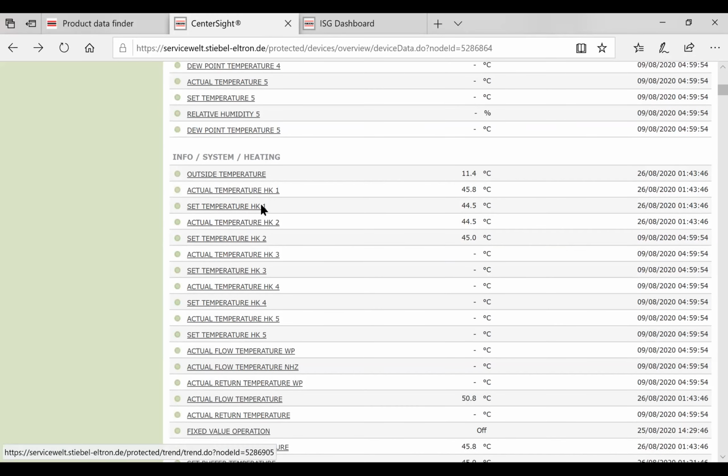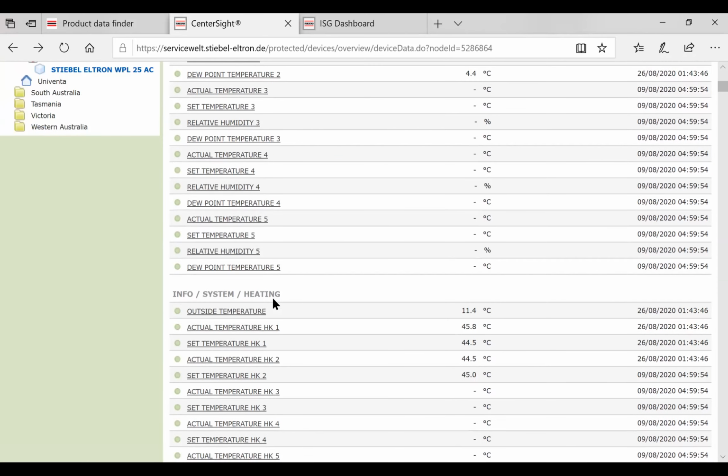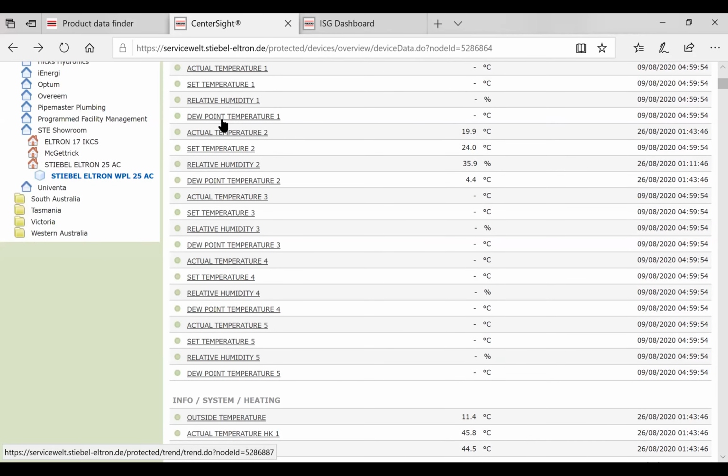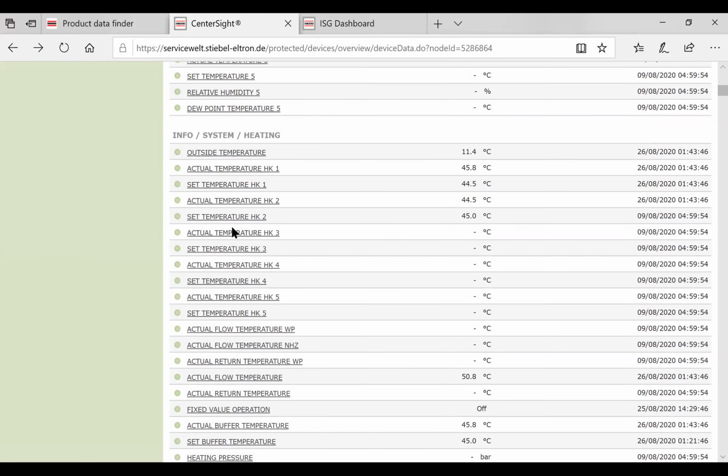We can look at every single heating circuit and see what the temperature set in that circuit is versus what the heat going to that circuit is. Think of a recent job, heating circuits. What I did was I looked at what the set point for a particular heating circuit was, and I looked at what the actual water flow temperature was, as measured on the sensor going to that section. And I could see it was all over the place. I'm saying the set point in the room says stop, but I'm still getting a call for temperature on the heating circuit. It's not right. I knew something wasn't right.